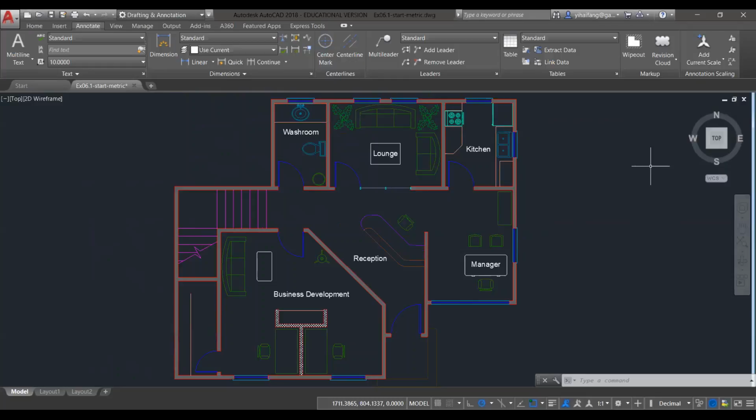Let's say you're making a robot, so there are different systems in the robot design. And say if you're designing even just a simple floor house like this, there are different components in the drawing. So you will have the structural system, electrical, mechanical systems, and piping. So if you draw everything on a single layer, you imagine what will happen. If you want to change something, you need to pick all the relevant shapes out and change their appearance or their property. So that's why in complex drawings, we want to use different layers to help us organize the objects.